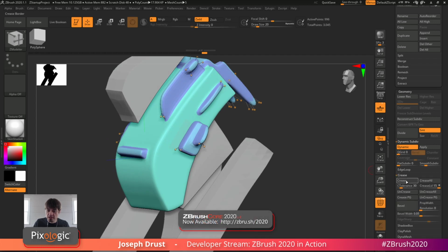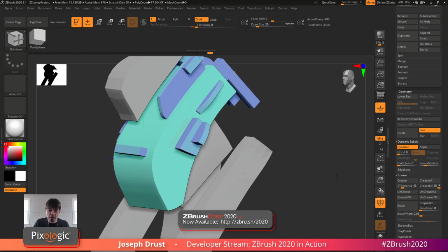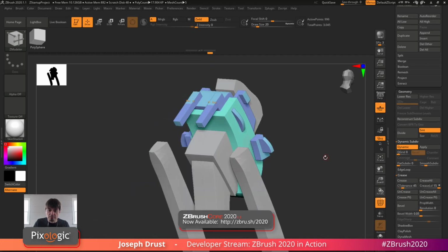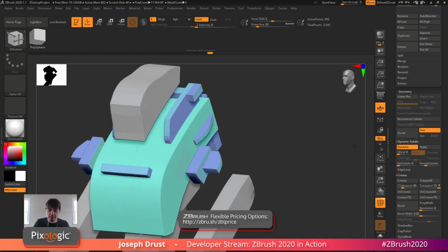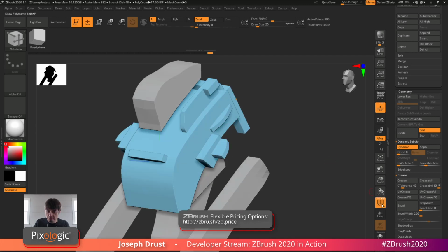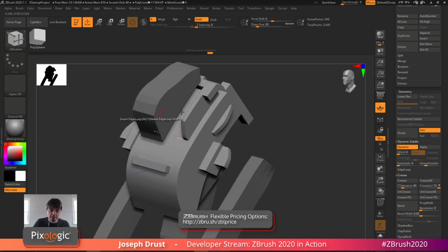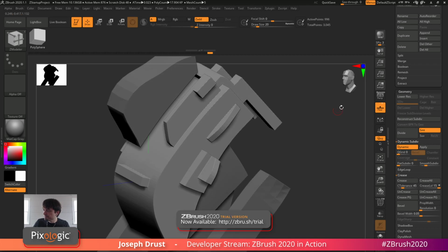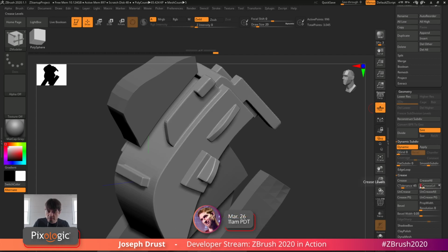So I'm going to go to Crease, and I'm going to set my crease tolerance to 45, and then click Crease, and that is now going to apply some creasing to my model. And so now I'm getting this happening, a little bit different result. I'll change my polyframe and turn back to, say, Matcap Gray. Now here I can change my subdivision slider and also my crease level, and this will determine how much smoothing is going to happen.